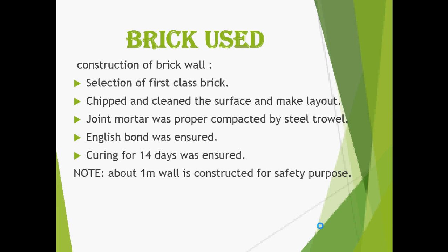Now coming to the brick used, these are the major building blocks of any building. First class brick was selected and English bond was ensured, and it was held for curing of 14 days. You can see the English bond has been made.